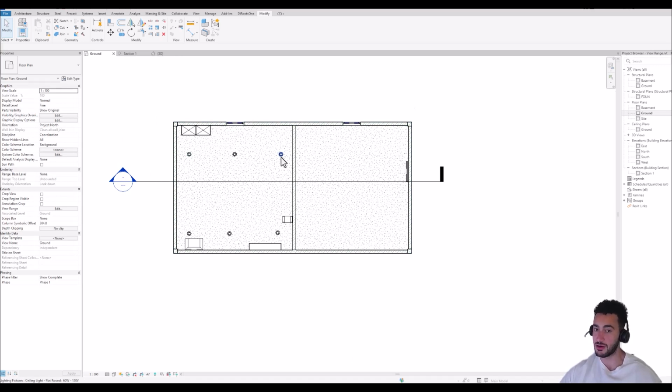So that's why you can see only the lighting, but not the ceiling, because the ceiling is going to be confusing for you, or it's not related to the architectural drawing that you're working with. Those priorities have been set. It's, I would say, a hidden setting inside Revit itself, which so many people don't know about.